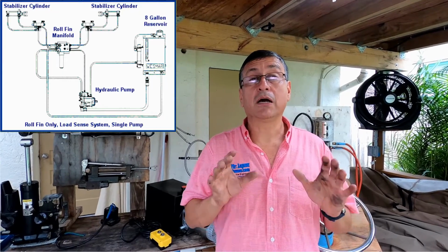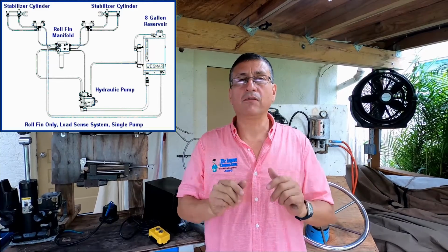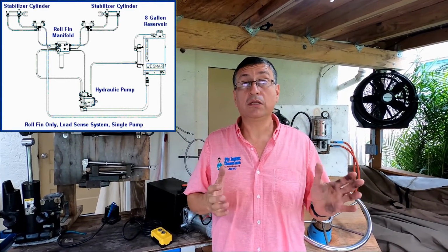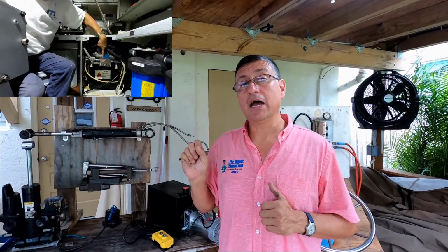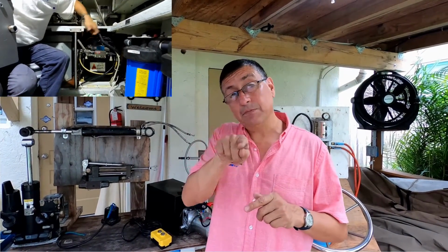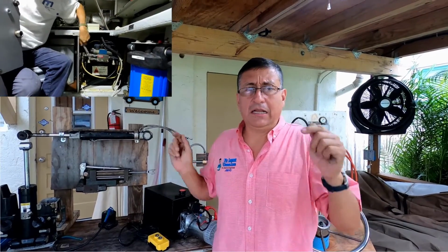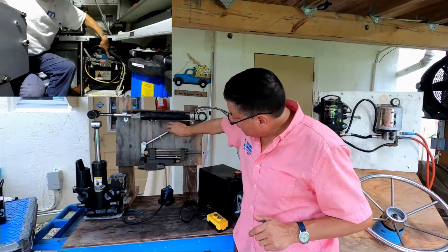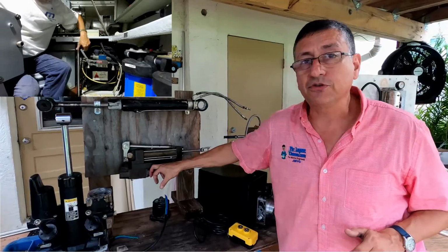Those diagrams are critical, because if you are the engineer of a boat and you have a problem, for example, with the trim flaps, you need to isolate the systems, and probably you need to go into the boat and move that particular actuator by hand, because the solenoids are broken or the signal is not coming in, and you need to go over there and with the handle activate the solenoid and move it to the other position.